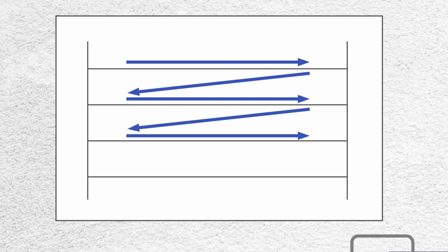In our example, we will place an open contact associated with the start button, then another open contact linked to the stop button, and finally a coil associated with the pilot light to close the logical circuit. When running this program, you will notice that the contact related to the stop button changes from open to closed without being pressed. This happens due to the physically normally closed NC configuration of the button. If you want a more visual explanation of this behavior, let us know in the comments.